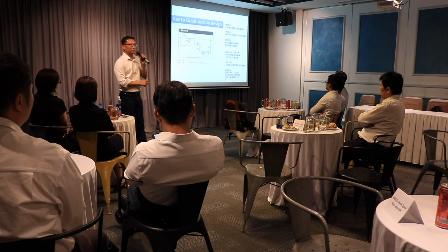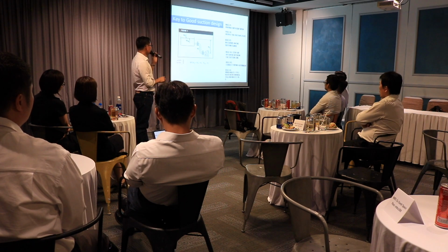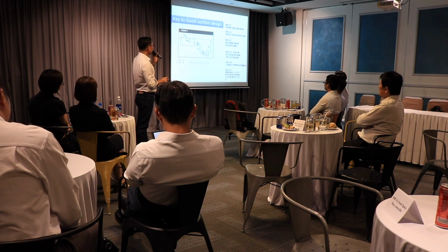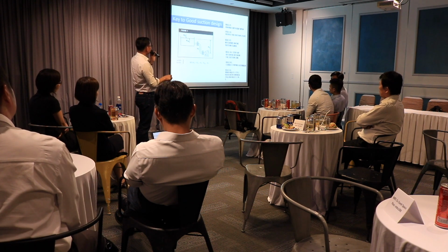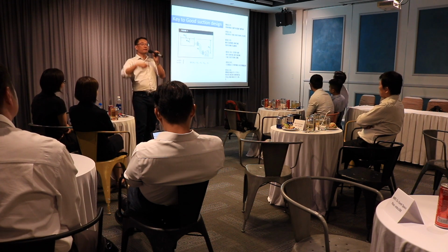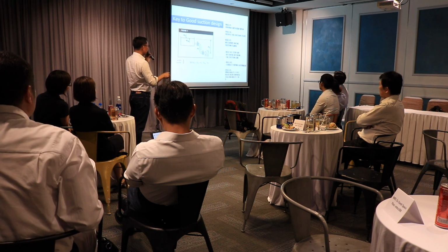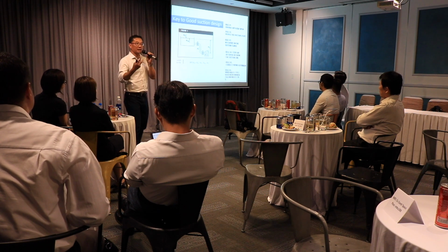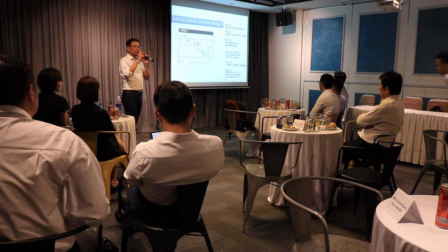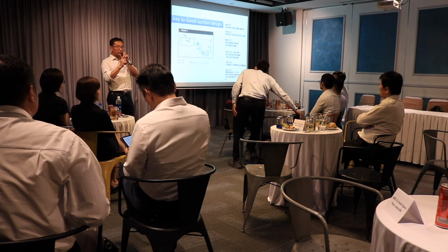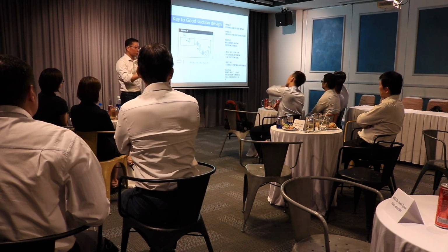A good suction design. This one, somebody told me about it. Rule number 1, provide sufficient NPSH. That means the suction line as straight as possible. Rule number 2, reduce the friction. That means you increase your pipe size. Rule number 3, no elbow on the suction, if possible. I don't think it's possible. Rule number 4, stop air or vapor entering the suction line. So the gasket, the valve, the packing on the valve must be tightly sealed. The other enemy of the pump is air going into the suction when you run the pump. It's actually not good for the pump.